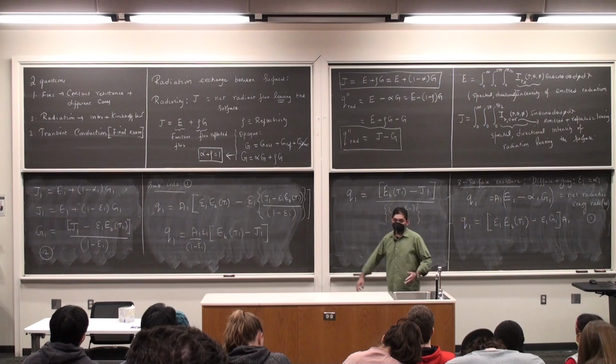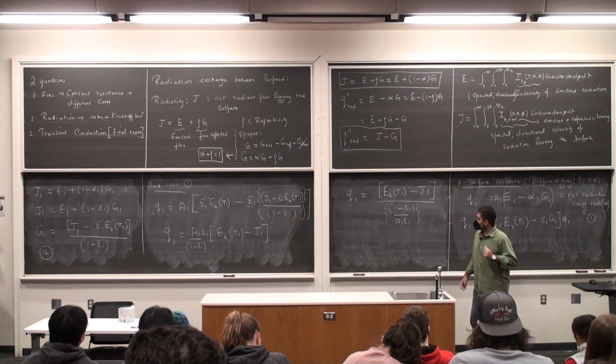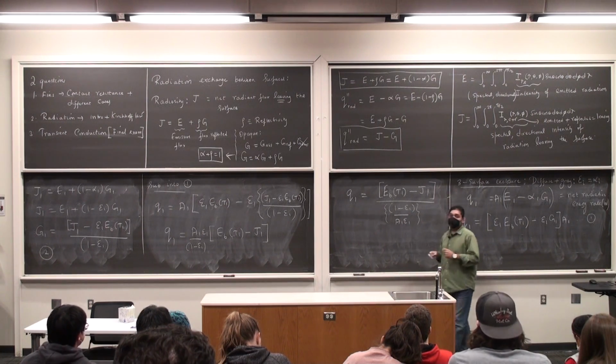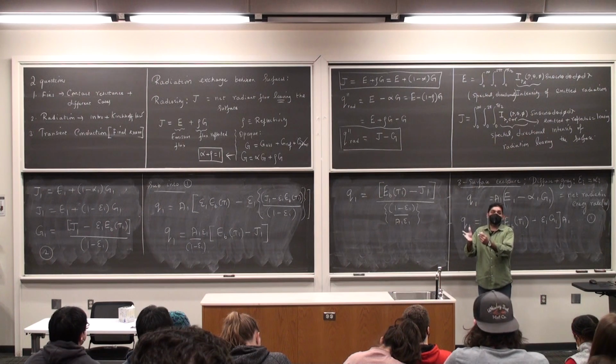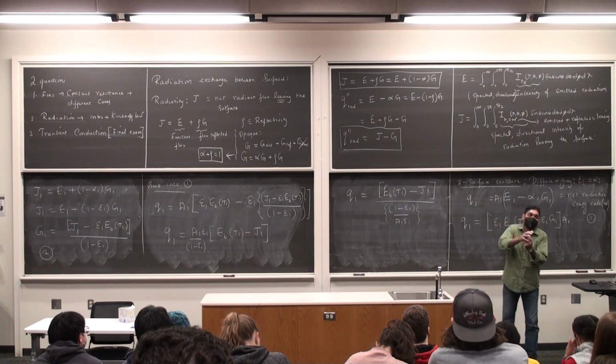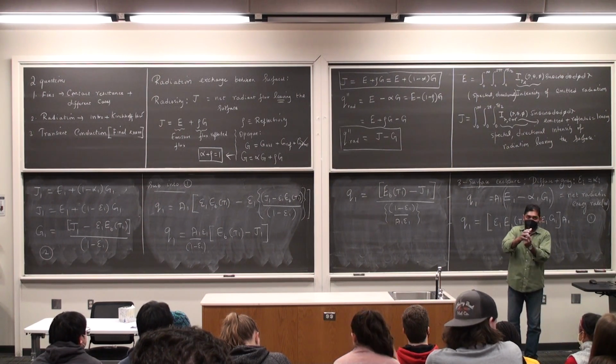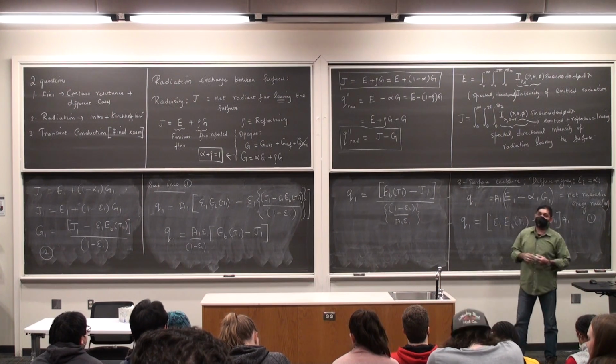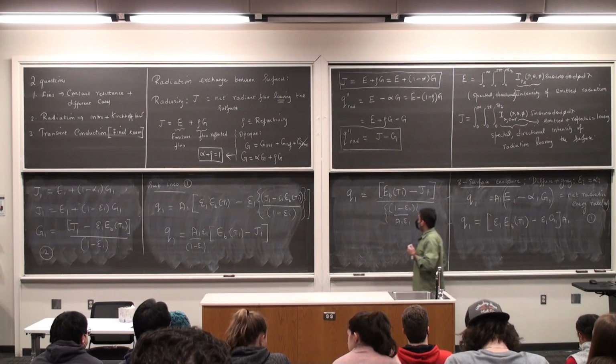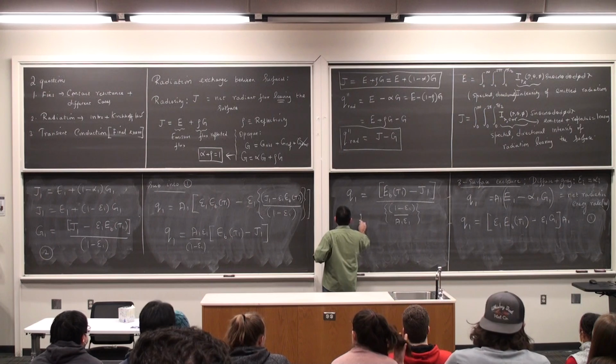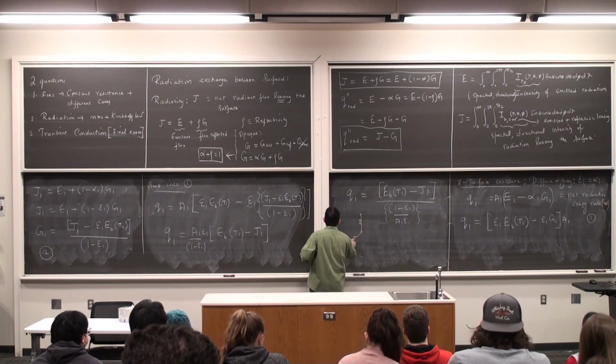And what we will show, very last second, is that I can have another equation which is going to be exactly similar to it, but with all the fractions coming into play, and I can then draw a radiative resistance network. It will look something of the following sort for the three surface enclosure.